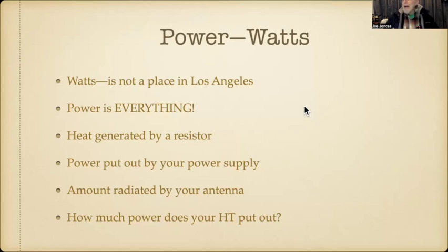Your power supplies that are in your shacks produce power. Usually it's 13.8 volts and hopefully up to about 20 amps, because if you've got an HF transceiver, it draws about 18 amps when it's putting out 100 watts.